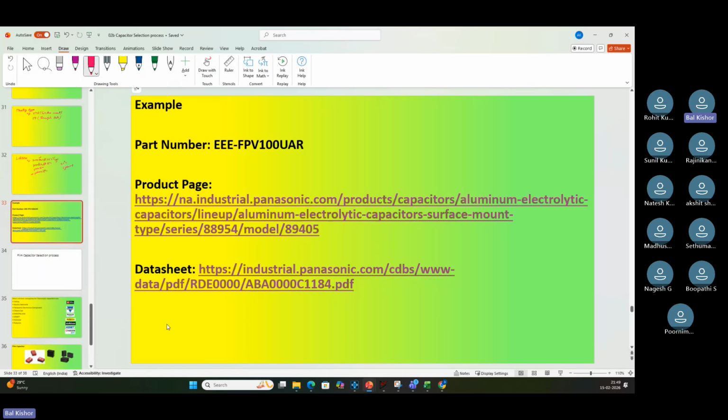One more advantage of ceramic capacitor is their lifetime is almost infinite, you can say. Okay, so they do not fail, but electrolytic capacitor will have a limited lifetime if it is running at higher temperature. So this is the main difference. Okay, other types of capacitors we will see later on. I'll send you the materials so you can have a look.